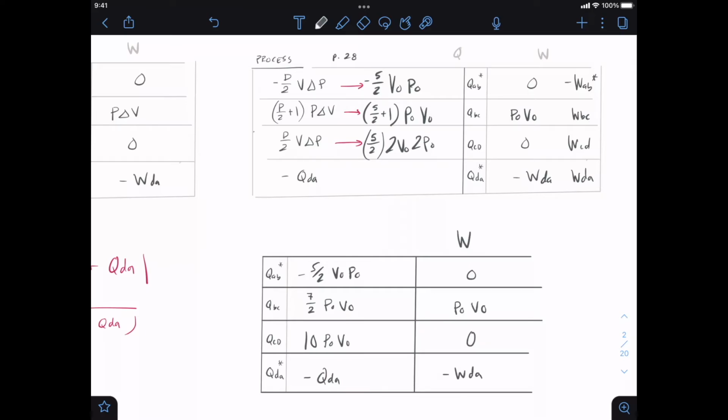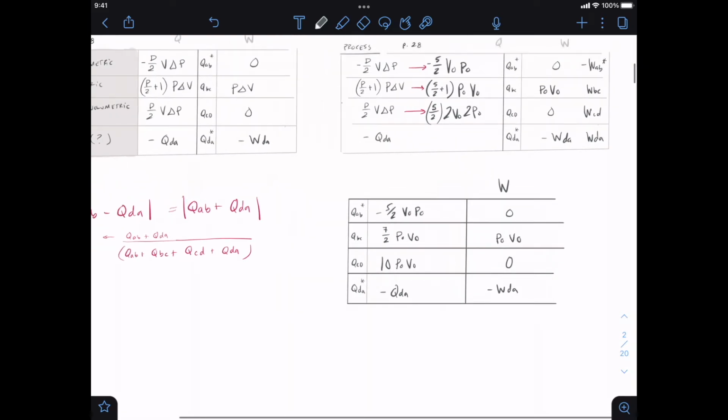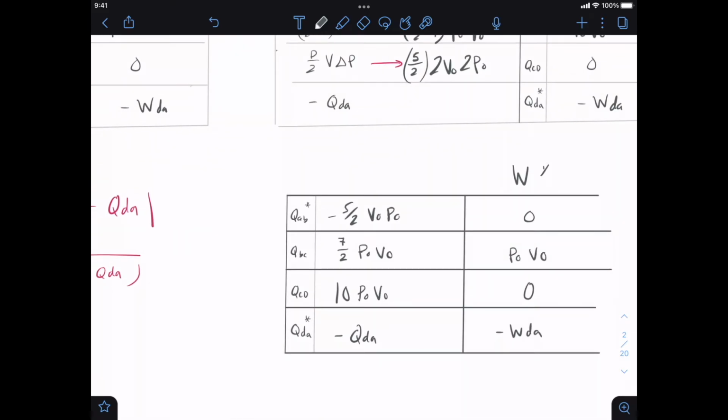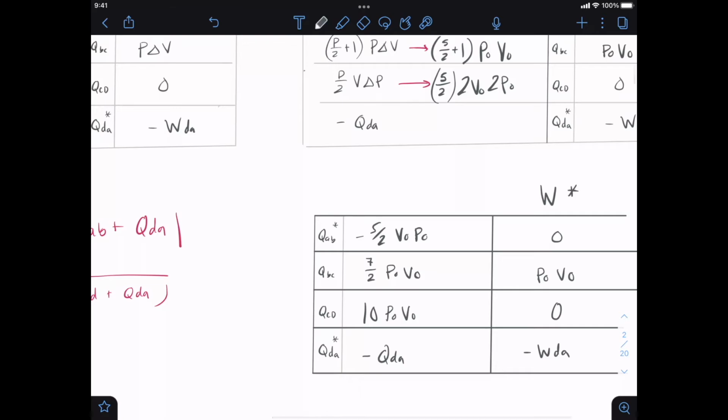Okay, cool. So what we're going to do, we want to find the coefficient of performance. So we're looking at the cycle. For the coefficient of performance, we're taking the work from the W cycle, which is going to be equal to the sum of all of the heat, and then QH is the heat supplied to the hot sink. We don't actually use this work piece here. They just had it in your solution, and I wanted to explain where the numbers came from, but it ends up not really being relevant for our particular problem.